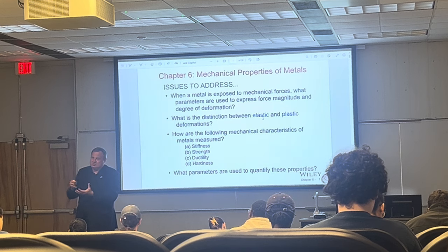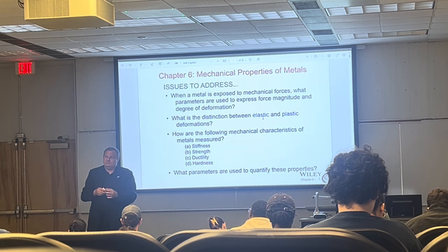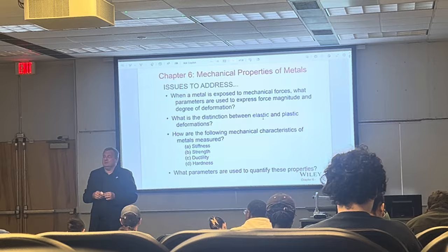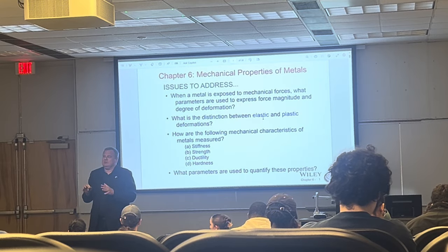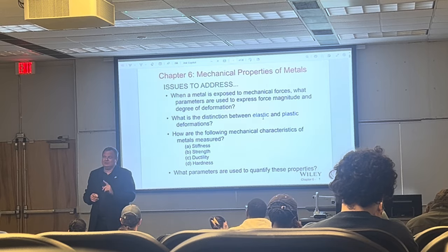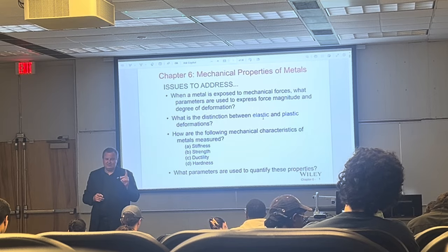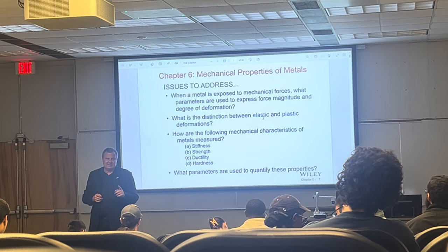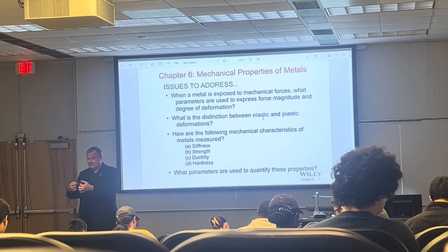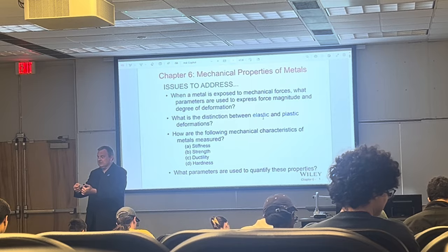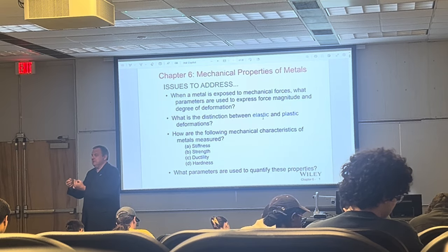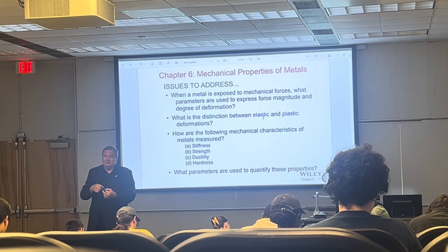But there's still some springing back. What I'm trying to say is that no matter what kind of deformation you have, unloading is always elastic. Unloading is always elastic. Write it down. Unloading is always elastic. If I have elastic deformation, the unloading is elastic. If I have elastic and plastic deformation, unloading is always elastic.